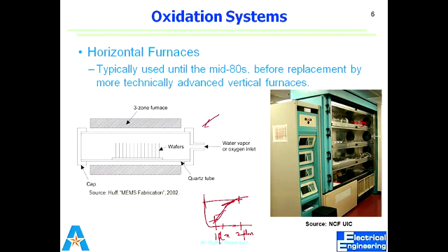In industry we have mostly four stacks of horizontal furnaces, and you see these are the furnaces. These are the openings to the furnaces, and these are the wafers standing vertically on the quartz board. That board is pushed inside the furnace for a specific time. The furnace is already at high temperature, and after that time the board is taken outside.